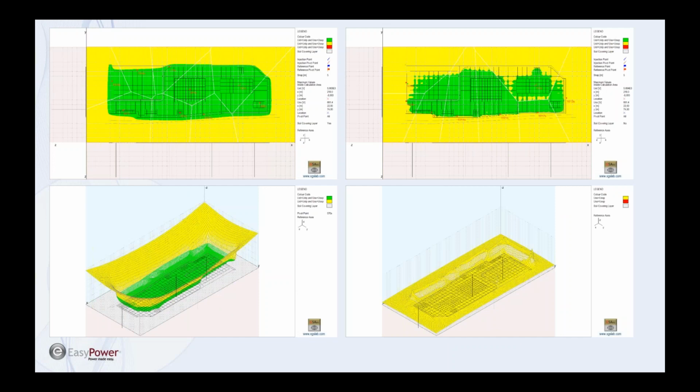Based on the ground potential rise that we just saw on the last slide, the program can do calculations for each 1 meter step, and each 1 meter, 2 meter, 3 meter touch within there, and it can do safety calculations for step and touch. The step and touch allowable voltages are calculated per the IEEE 80 equations.